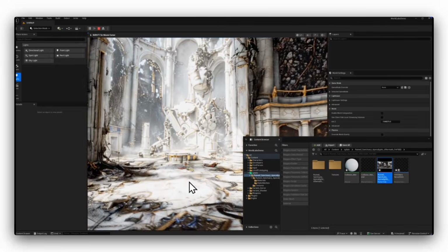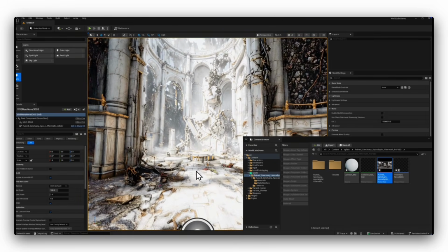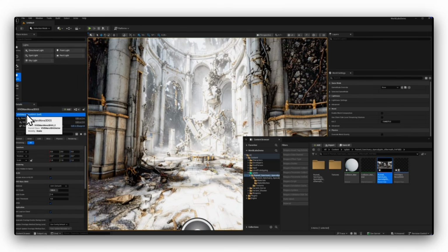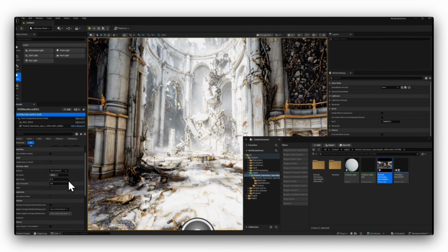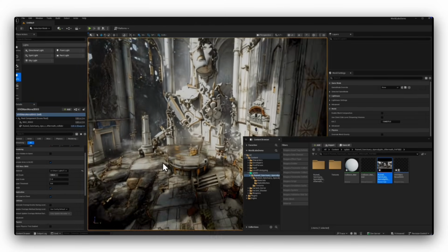But what if we wanted to do something a little bit cooler? Like if we wanted to add custom lights to our scene, how would we do that? So let's select our splat, and we want to select the root component, or actually we're going to stay at the top level of the VIVE Mars component, and we're going to come down here to the VIVE Mars 3JS divider, and we come to material, and select unlit. From the drop down, we want to select lit. And now we can start adding lights to our scene.